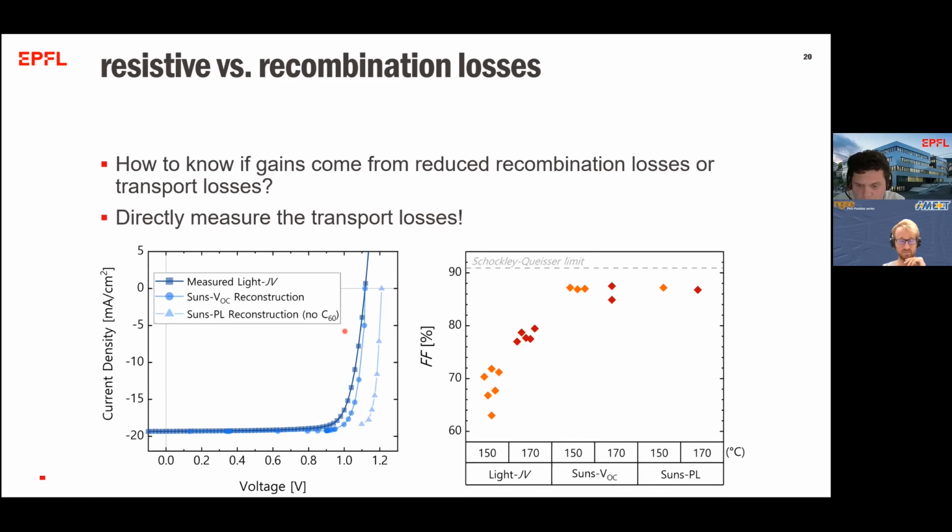And what you can learn from that is basically that we have removed quite a bit of the resistive losses by this high temperature annealing, but we didn't remove the interfacial recombination losses. So interfacial recombination is still the problem. We could, in principle, go a little bit higher in fill factor, but this loss here also translates to a loss in transport and extractability of these charges, so recombination loss around the maximum power point, which we haven't solved yet.